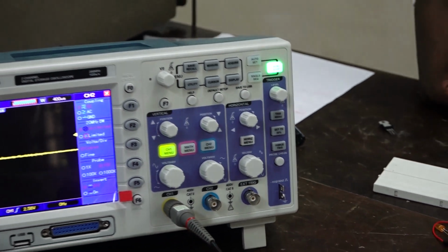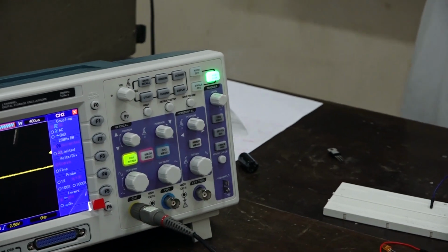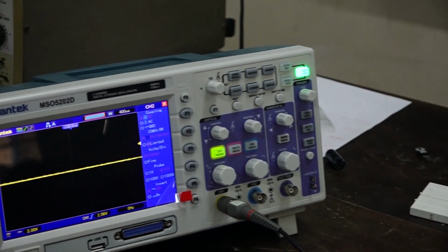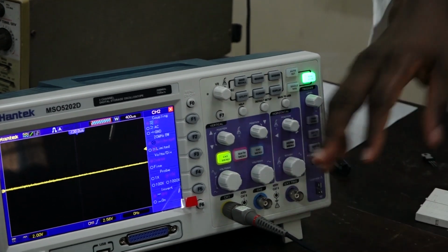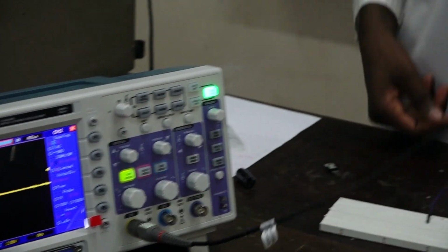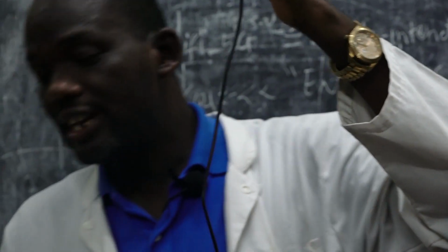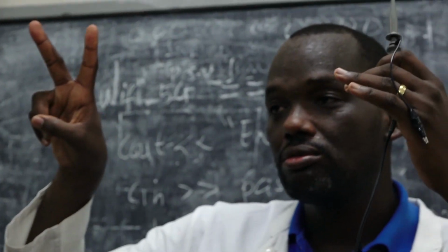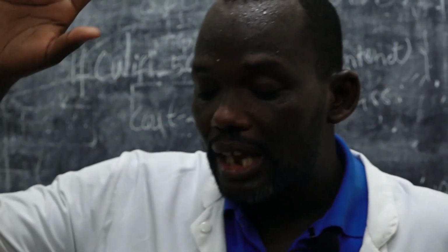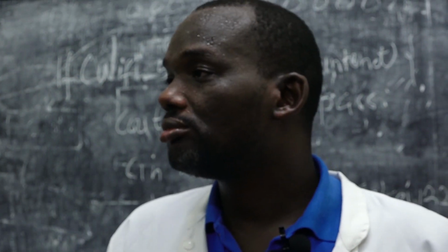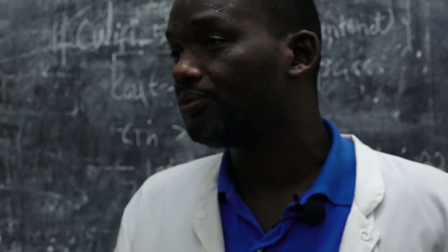May I repeat? I say the second process that we are going to do now is to set our digital oscilloscope. The way we do it, we have to connect the BNC probe into one of the channels, whether channel 1 or channel 2. But the goodness is this digital oscilloscope comes with 2 probes, so you may connect one probe in channel 1 and another probe in channel 2. You are not limited. It depends on the measurements that you want to do.